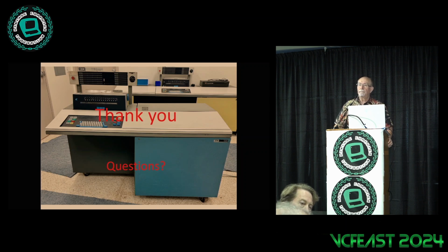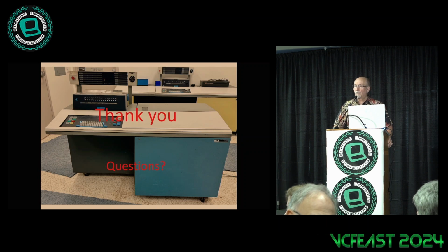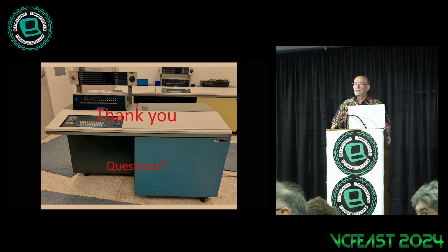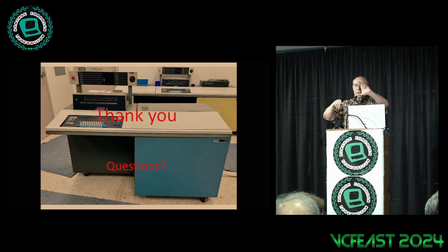So I have a question about the power supplies. You mentioned it was the ferro, what was it again? Ferro-resonant. So you were describing how you basically saturate it, right? So that if the input voltage goes above a certain threshold, it won't pass through, it will keep it to a certain level. But if it's lower, it won't pull it up to the right level, right? Well, you will saturate it below the target level. So basically, there's a relatively wide range above and below.